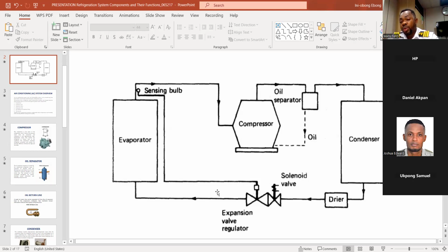It could be that your evaporator fin is choked up. It could be that the evaporator fan is not working. If it uses an electric motor, it could be that the motor is not working. And of course, it might not really mean that the motor is bad. There's a capacitor attached to that motor, and that capacitor might be bad.